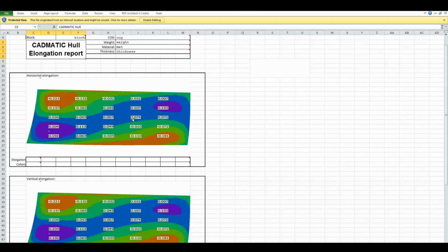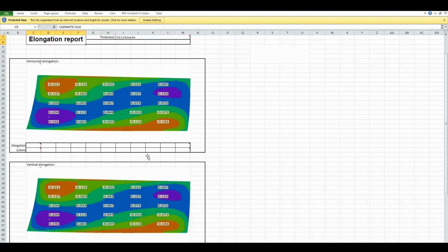In the elongation bitmaps, the flattened shell plate contour is depicted in black, and the marking lines of the inner construction templates are depicted in white. The remaining shell plate surface is filled with colors depending on the local elongation. The local elongation is transferred to a color by using defined rules in the system management, which we will see in a moment.